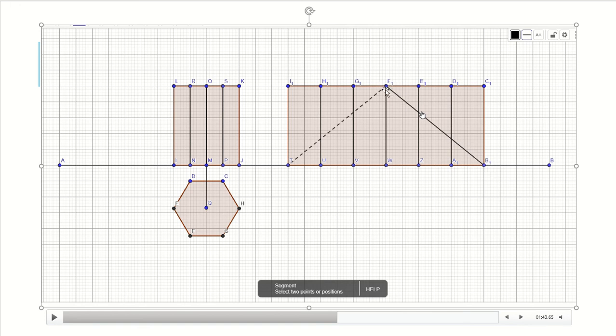Fine. Similarly, go for a hidden line over here. That means it is again diametrically opposite corners. Fine. Now you can see you are getting some points on these edges, right? Transfer that horizontally to the front view. After transferring it, you will get the final route of the ant. Please watch this video.